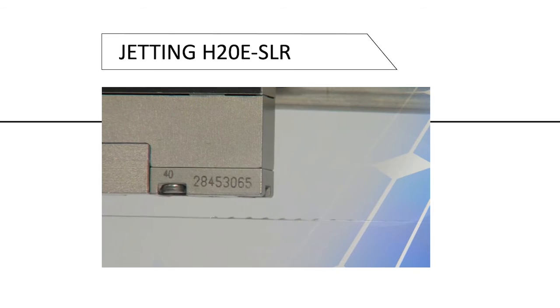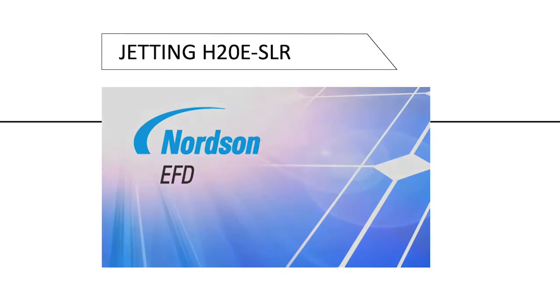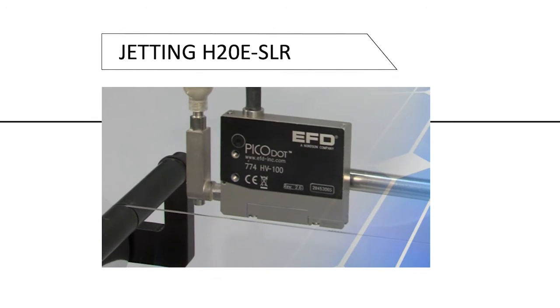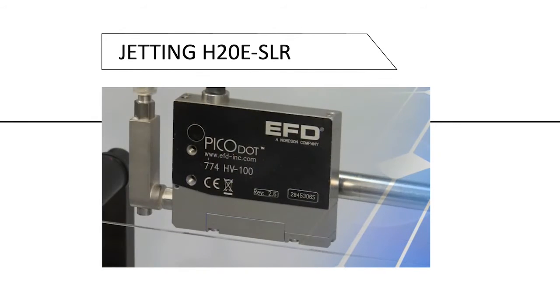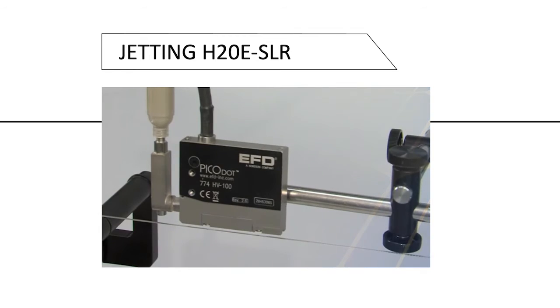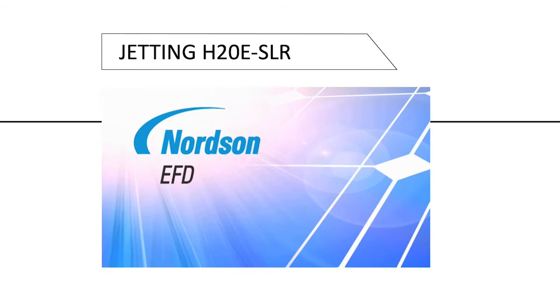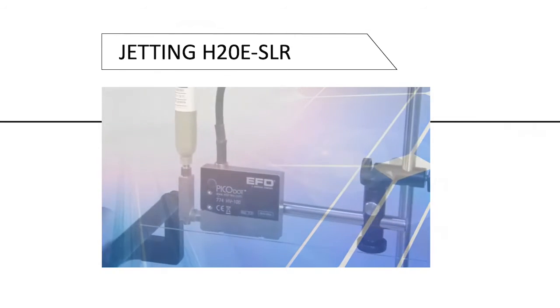As the video zooms in, you can see tiny silver dots being rapidly deployed onto a solar ribbon. In this solar stringing application, they utilized small dots of silver adhesive rather than long lines. With the speed of repeatable dots they needed, jet dispensing was by far the best solution for this particular application.